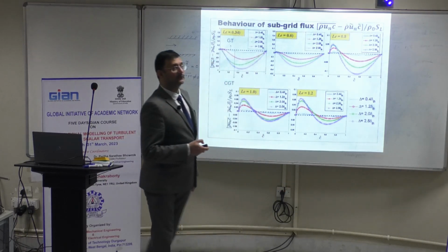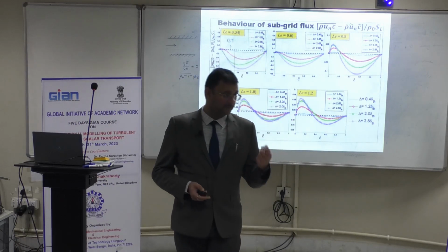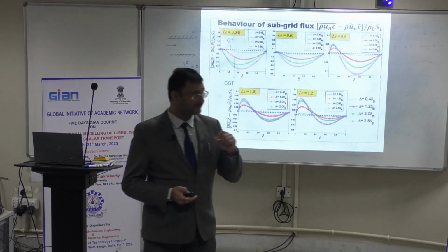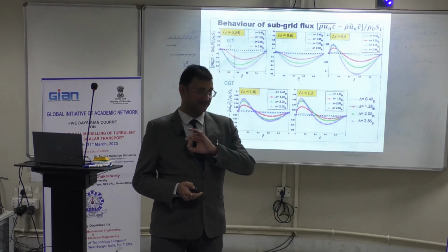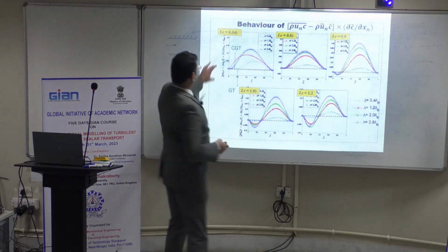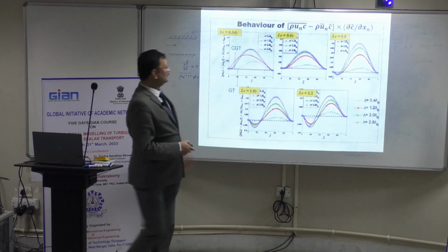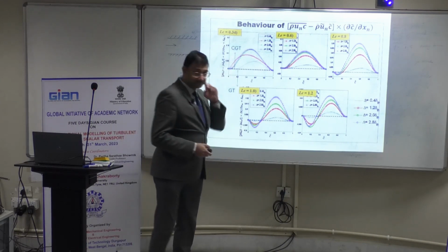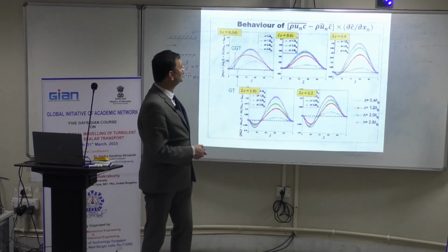Okay. So the behavior in the case of LES is also filter size dependent. Keep that in mind. That aspect was not there in the context of RANS. Product of the scalar flux and scalar gradient, now positive value is counter gradient, negative value is gradient transport.